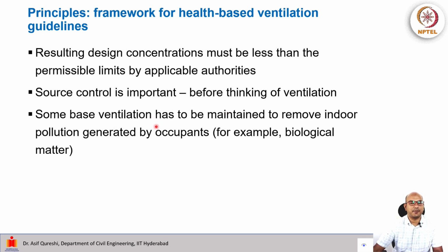Having said that, some base ventilation has to be maintained. This is to remove whatever indoor pollution is generated by the inhabitants. For example, we may be emitting microbes through our breathing or through shedding from the skin. So some basic ventilation must be there to remove this kind of microbial load, and maybe also some base emissions of other chemicals. So we have to maintain some base ventilation all the time.